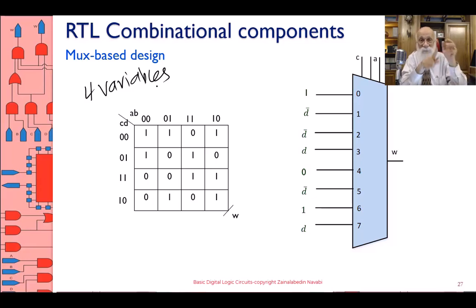That one variable will either be 0 or 1, or that variable of these 4 variables of the Karnaugh map, or the complement of that. This way, I don't have any logic on the side of my multiplexer. Again, 4 choices for the inputs of the multiplexer: 0, 1, that variable, and the complement of that.